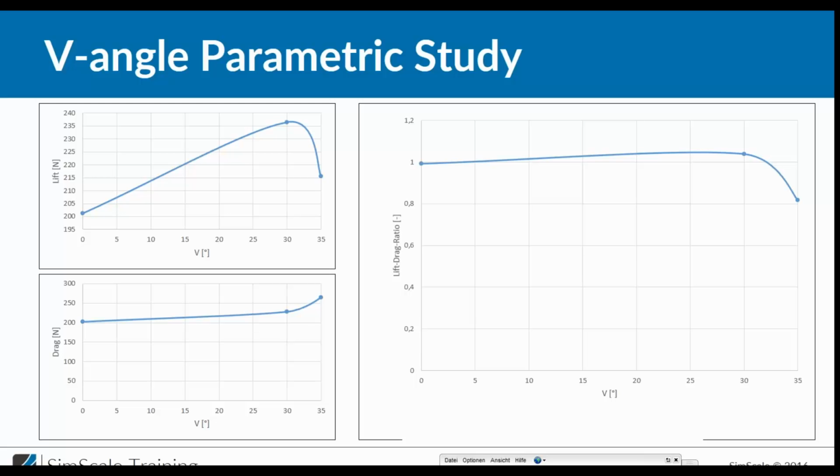And the interesting thing on top of that, because when we judge the performance of an object, we can't judge only with lift force, but we also have to relate it to the drag. We can see that, of course, if you increase lift force, you will increase drag, but the idea is how much you will increase the drag. And we can see clearly that the drag increases, of course, when you increase the V angle, but it's not really a significant increase.